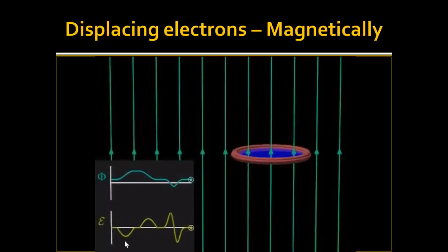It's interesting to point out that when you use a magnetic field in motion to get electrons to move in the conductor, that electron flow produces now a magnetic field that opposes the one that produced it. It's called counter EMF, CEMF. This takes a little bit of pondering, but the important thing to remember is if you have a conductor and you have a magnetic field and you place them in proximity, if you move one, it's going to affect the other. So you're going to get movement of electrons in that copper wire, whether you move the copper wire in and out of the field or move the field back and forth across the copper wire.